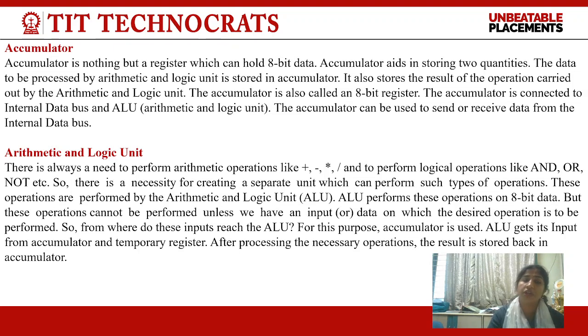But these operations cannot be performed unless we have input data on which the desired operation is to be performed. So where does this data reach the ALU? For this purpose, the accumulator is used. As I already told you, the first 8-bit data which needs to be added, subtracted or multiplied has to be provided to the ALU through the accumulator. And after processing, the 8-bit result is stored back in the accumulator.